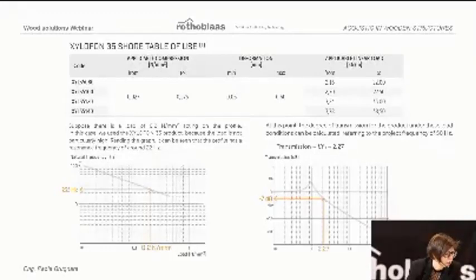After the estimation of the load, we can enter into the graphs here. Knowing the load, for example 0.2 Newton per square millimeter, we can estimate the natural frequency. At this point, we can divide the design frequency, in this example 50 Hertz, by the natural frequency. With this value, in this case 2.27, we can enter into the graph of the transmissibility and estimate the acoustic benefit. Sometimes you can find a table of use of the resilient profile.